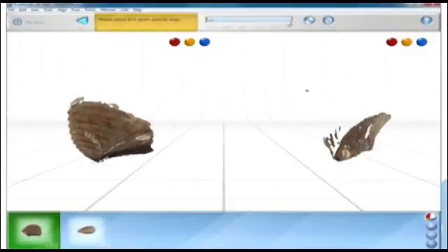The next step now is to merge those two scans together, and you use this screen here. So you're seeing one of the scans on the left, the other scan on the right, and all you have to do is to tell the computer roughly how they align. It will do all the details, but you need to show it roughly. And to do that, you have 3 colored pins, and you simply have to drop those onto each of the models to show equivalent points.